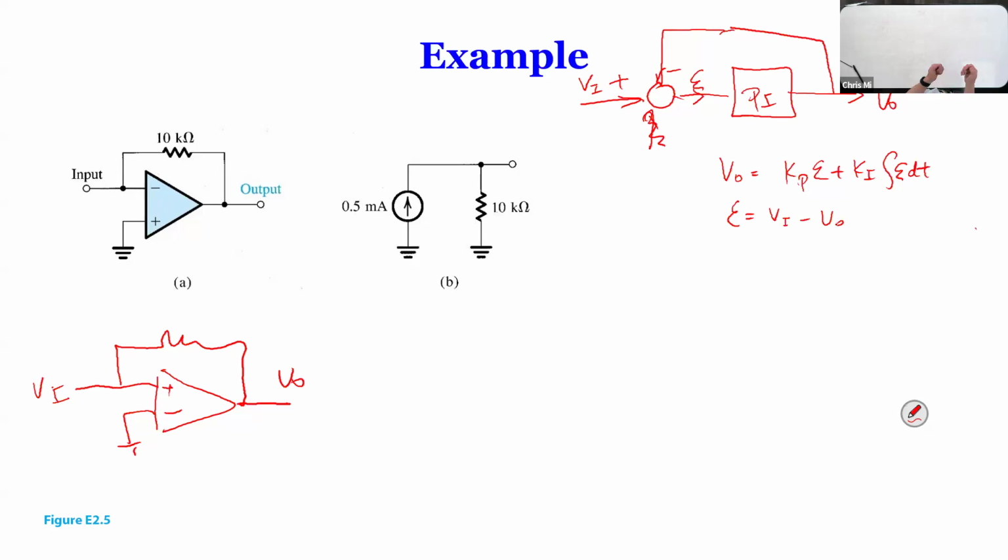If you use cruise control, the system does it for you, so you don't have to press the brake or the gas pedal. The cruise control looks at your vehicle speed and your setup. If your speed is too fast, it will reduce gas or apply brake. If your speed is too slow, it will accelerate with gas. That's exactly a control. But if you have positive feedback, you're going to have trouble.